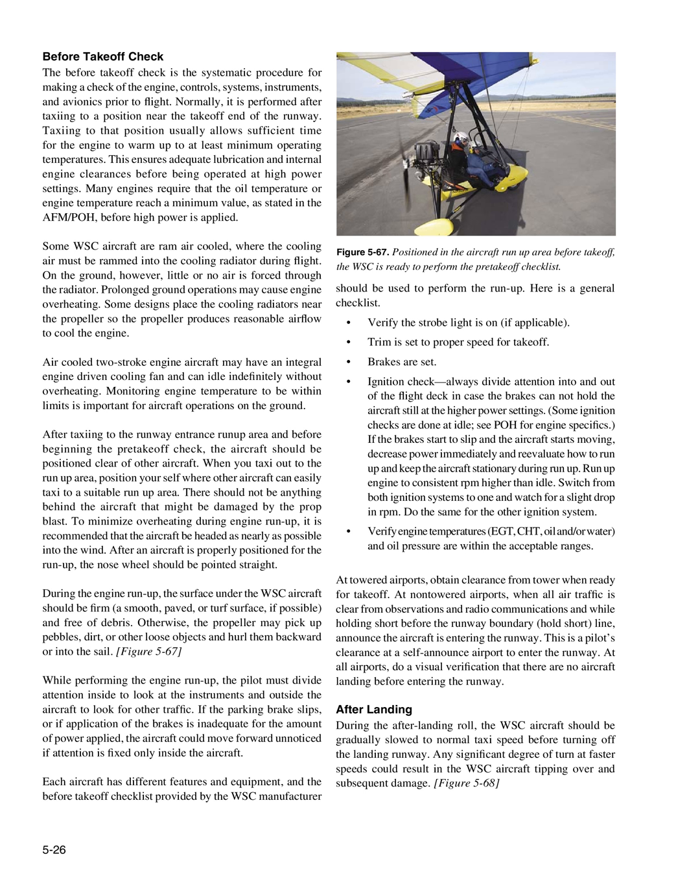After an aircraft is properly positioned for the run-up, the nose wheel should be pointed straight. During the engine run-up, the surface under the WSC aircraft should be firm, a smooth, paved, or turf surface if possible, and free of debris. Otherwise, the propeller may pick up pebbles, dirt, or other loose objects and hurl them backward or into the sail.